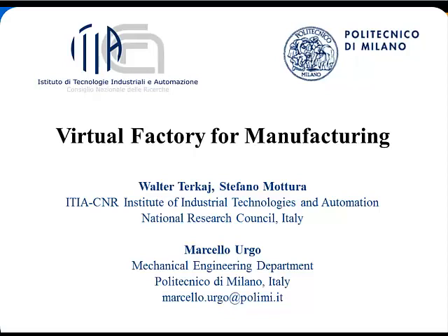Another kind of performance indicator is related to the time performance of the execution of the manufacturing process. Every time you have a manufacturing step, you have a theoretical time, and then you have an actual execution, and we have a way of collecting the actual execution time for all the process steps. Then you can compare it. You have a statistic, say that on average it took 10 minutes to perform this kind of process step, and then you can compare with the theoretical one.